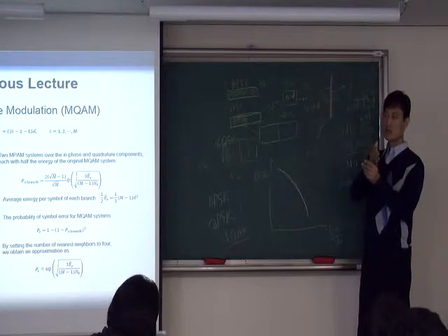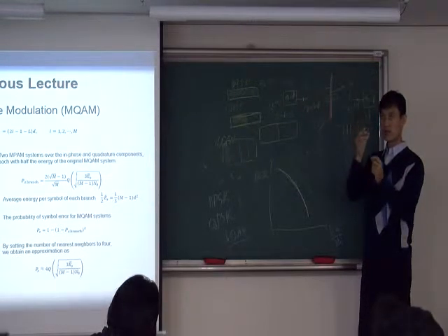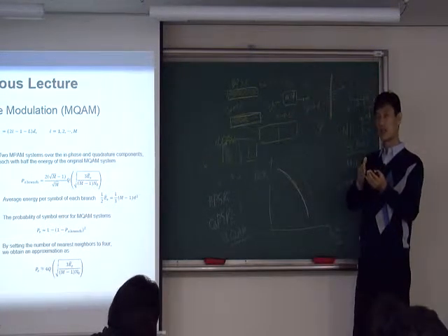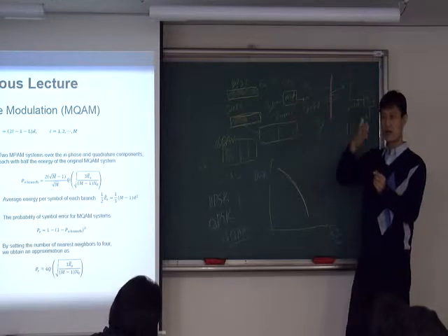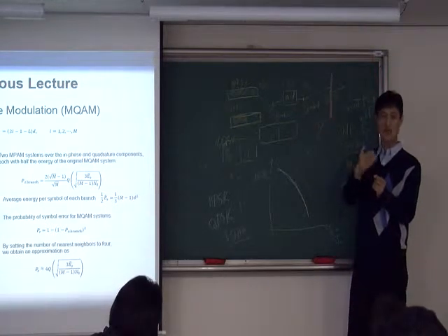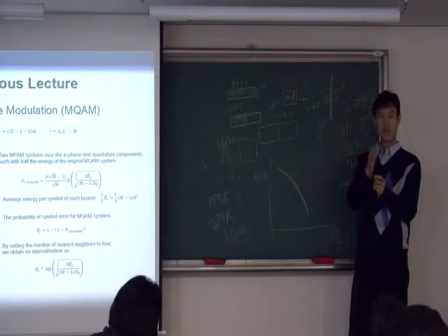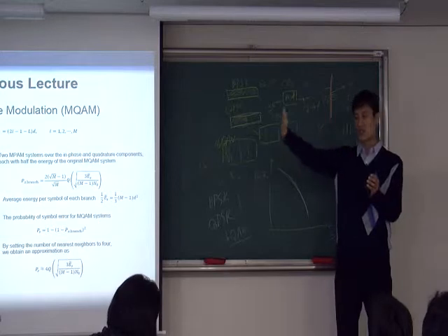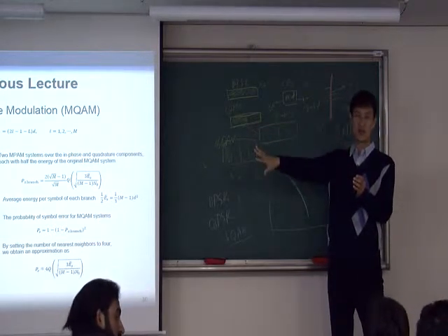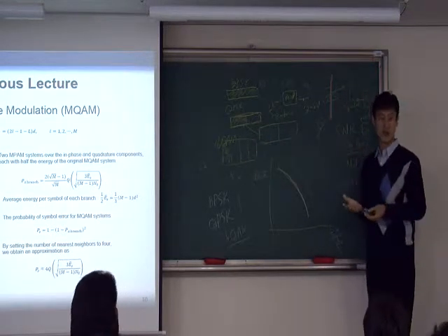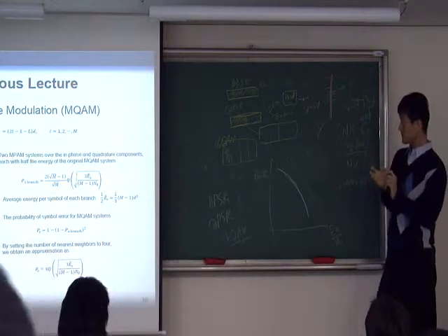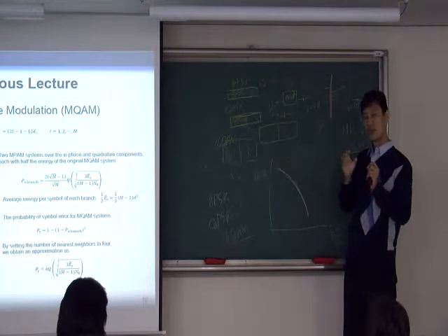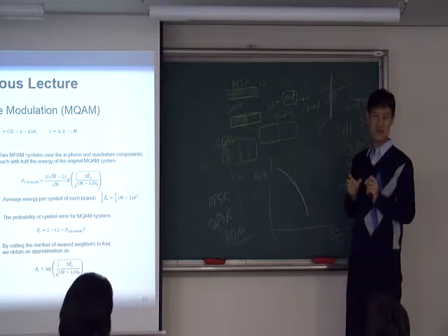Because when you multiply certain frequency, now think about that. When you multiply cosine by cosine, there will be harmonics. Let's say FC is the carrier. When you multiply by FC, mathematically you will get FC, 2FC, you have harmonics. So you have to cut off the harmonics by a filter. You should have a filter whenever you have a mixer. But what I'm saying is that after the mixer, what you need to have is the power amplifier.